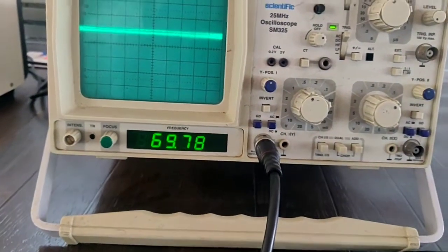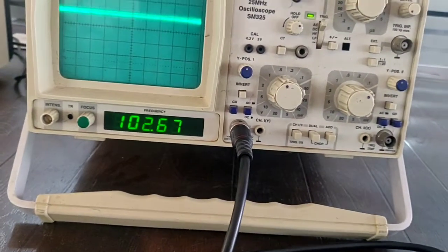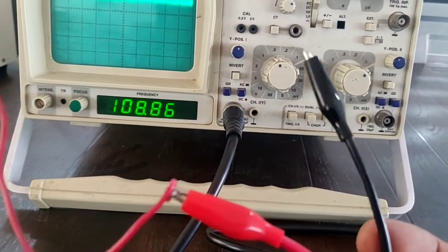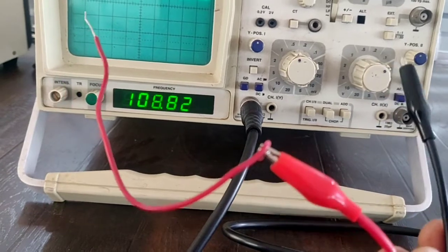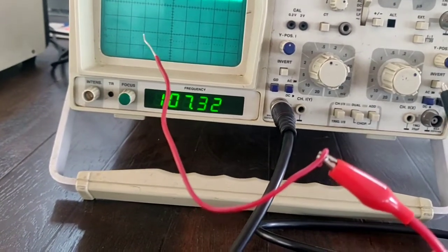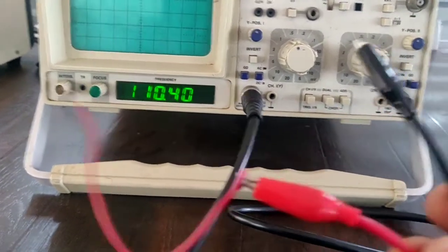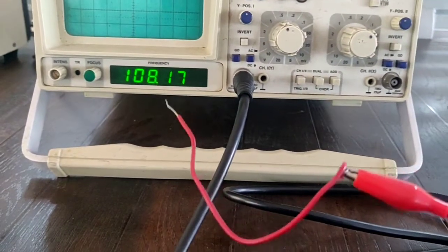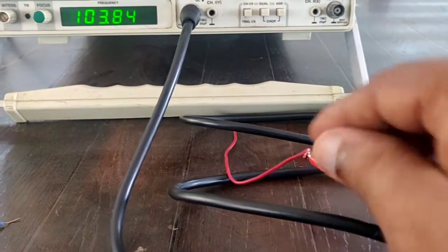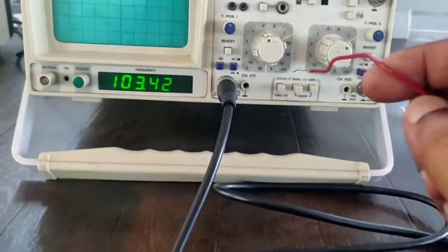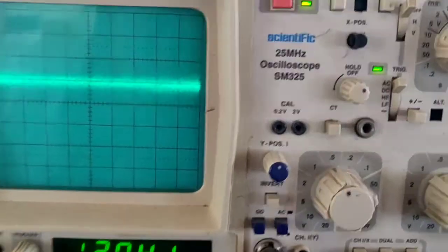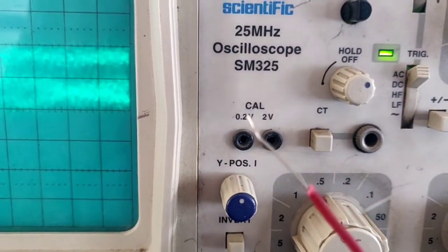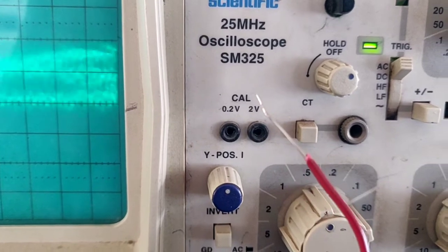Next, in the CRO probe you can see there are two wires available here like this. One is positive, another is negative. The first thing is you have to check the positive terminal condition. Both the terminals are important. Anyhow, first we are going to check the positive terminal. So select the positive terminal here, and there is a calibration option. Each and every company has provided what is called calibration here. Can you see that?